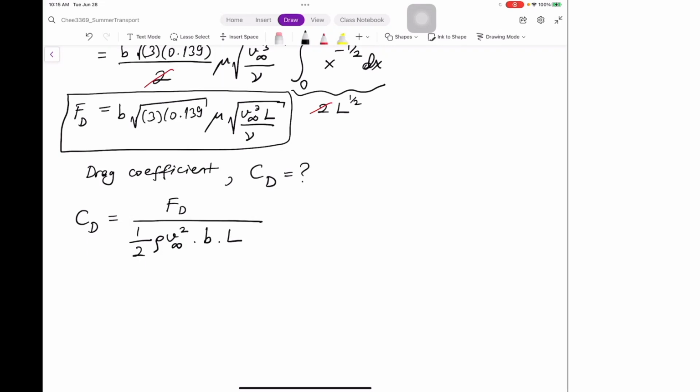It's basically, this is more like an average, right? As you know, drag coefficient. Similar to CF, but you're basically taking an average approach, like you're taking average shear stress, the drag force, divided by the entire BL instead of infinitesimal tau W. Okay, and we can estimate it.